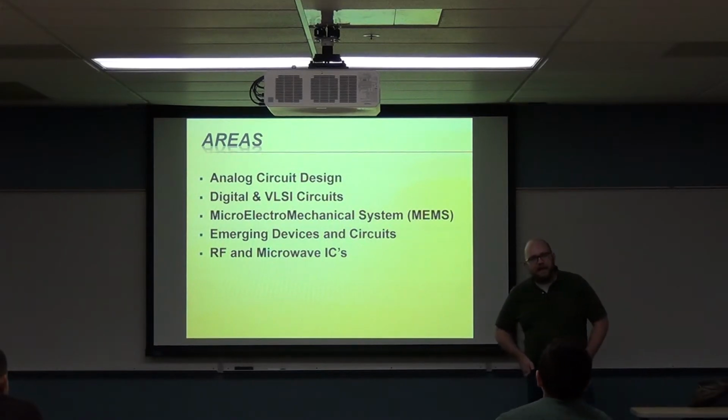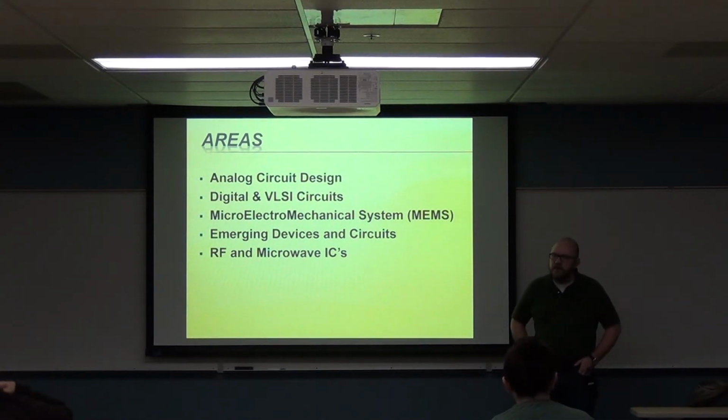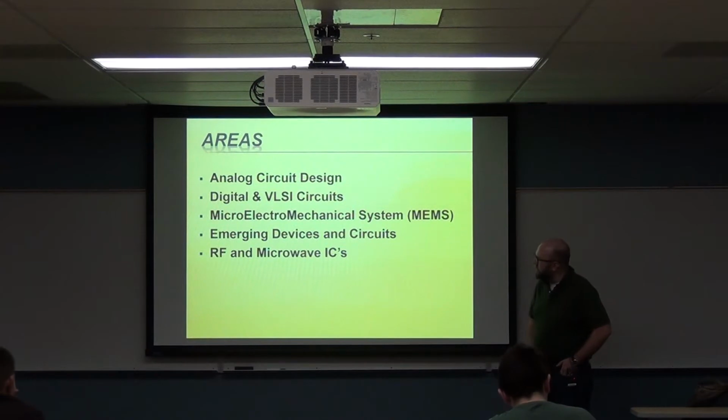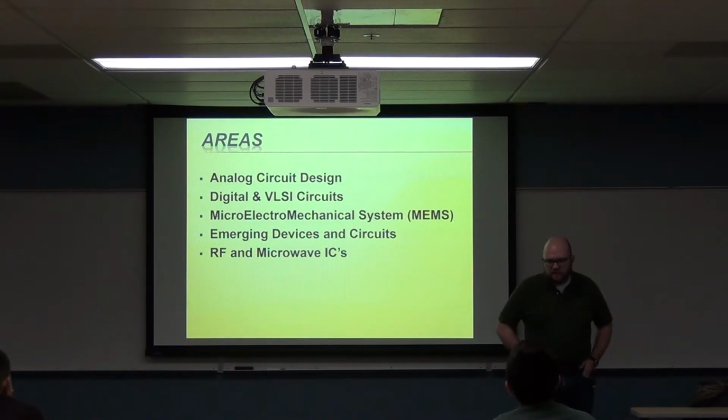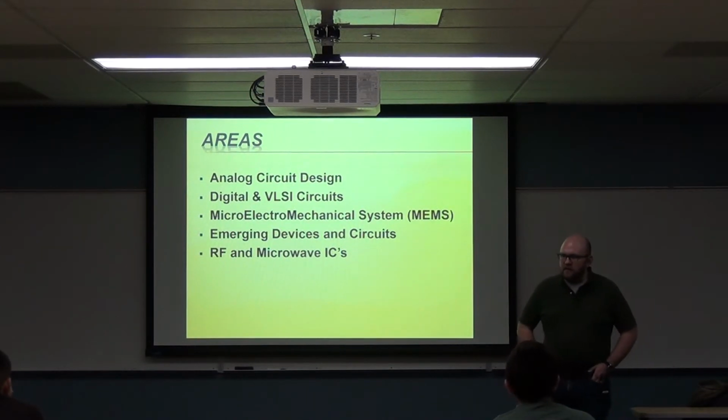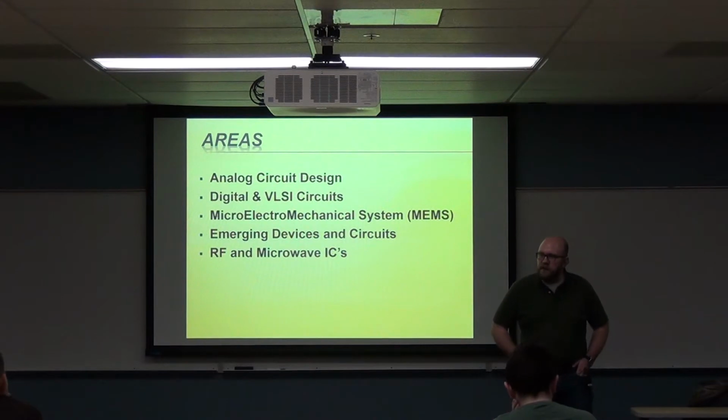So after we've done all this effort to actually integrate things at super fine scales, we realize that there's significant value to integrating other kinds of devices. The very first thing you might think is, what if we had mechanical actuation or mechanical movement? What could we do with those? What could we sense with those? Accelerometers sense deflections in beam arms inside the device to tell it where it's moving. Gyros have a similar thing where they're sensing deflections in beam arms to measure the rotation.